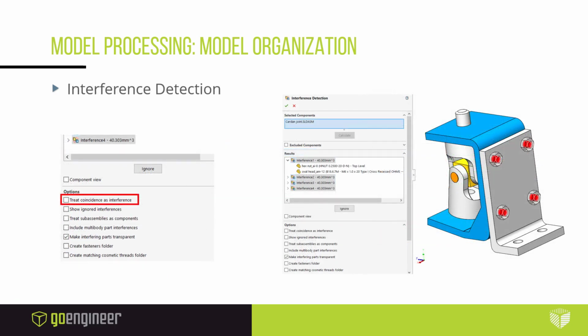The last tool I want to review with you all for this last section is checking your model for any model interferences. CAD geometry can easily be created in interference with other model bodies, or also when there is a translation error when the model is imported and translated from one modeling kernel to another. If a model with interfering bodies is brought into simulation, this can cause errors in the calculation of the mesh or instability in the calculation of your solution.